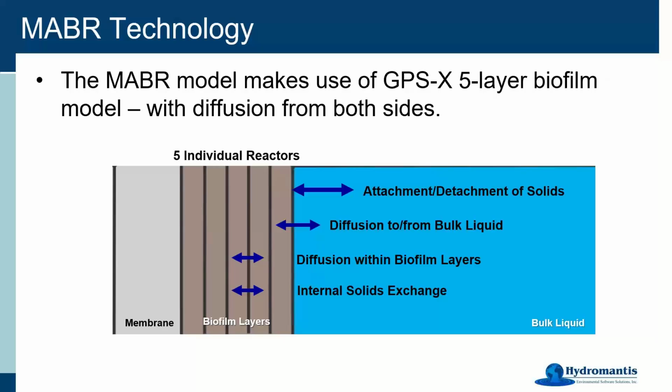Okay, so that is what is going on in all of this. Oh, sorry, and I forgot, the other important part too was, of course, the diffusion of gases across this membrane surface here. Primarily the main one that we're worrying about is, in this case, oxygen, but we do also take care of the other gases, mostly because we have to mass balance the gas across the entire thing altogether anyway. So one of the key things is to specify this oxygen mass transfer coefficient that is appropriate. And that is a parameter that you can calibrate and an important one to consider when calibrating your model.